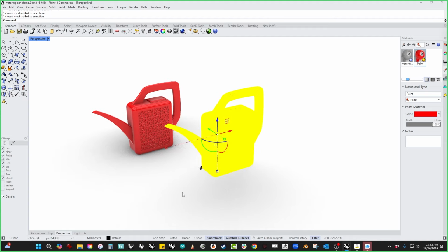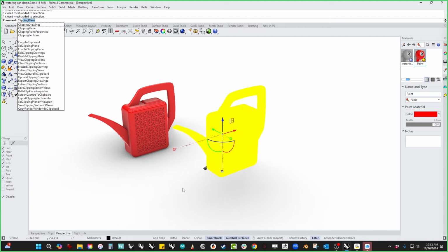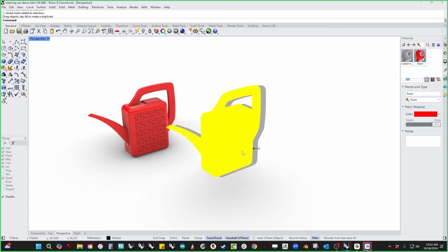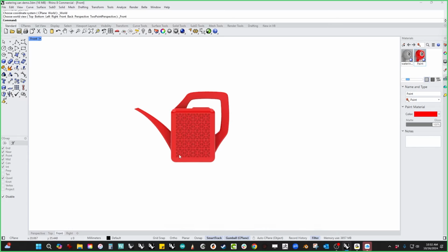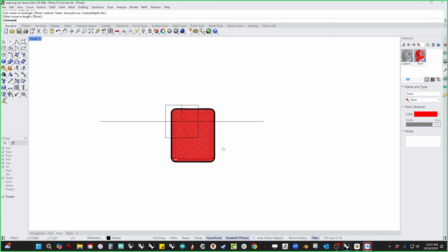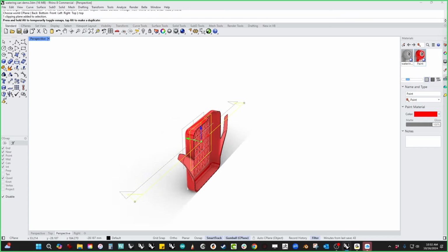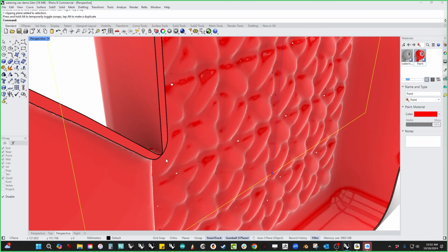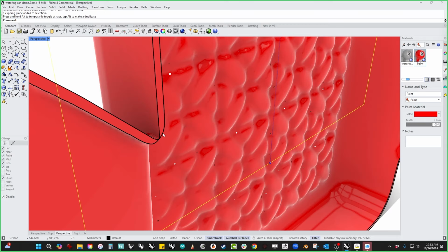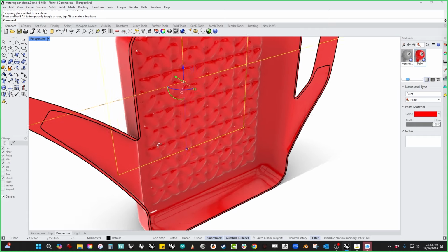I think actually when I was showing the clipping plane, if we're going to be completely transparent here, I think I over smoothed it a little bit in that area and it got thin. Let's take a look. And the fix is to just give it, yeah, see how it got thin right there? So I didn't give it quite enough resolution to get down into that corner. So I should have lowered the target polygon count, or lowered the target edge length enough so that it added a few more points in here. So just pay attention to that kind of stuff.